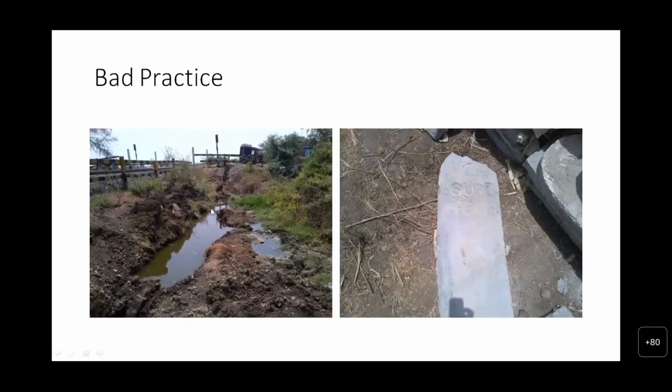And when the marking was given, in this case, the trenching was done at a place near the drainage. Due to that, before laying the cable, water got into the trench, and this sort of marking shall not be given to the executing agency.